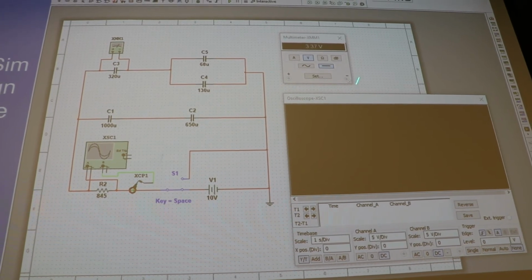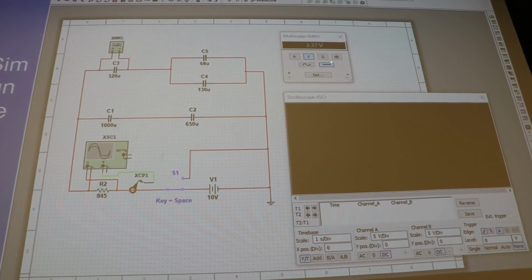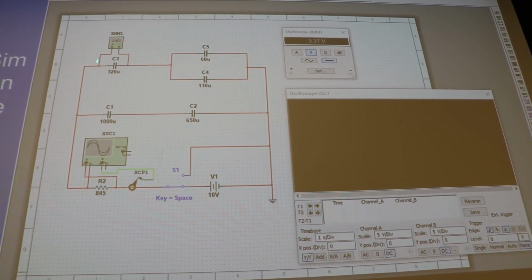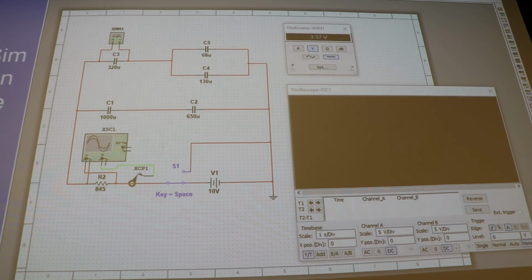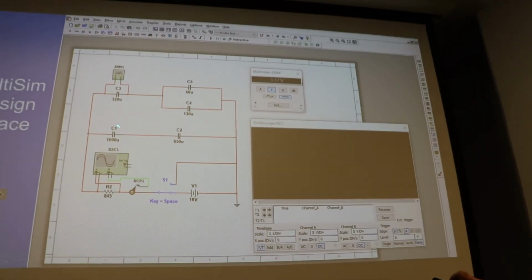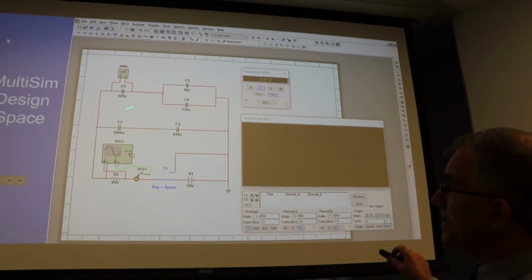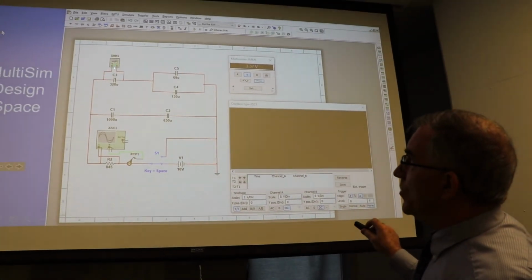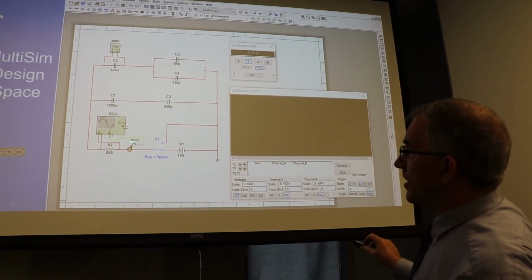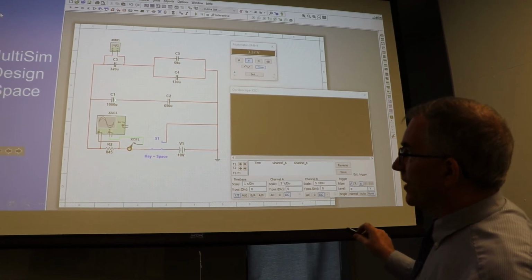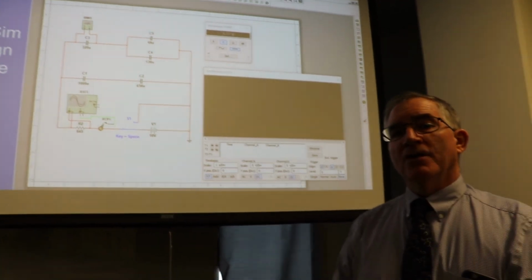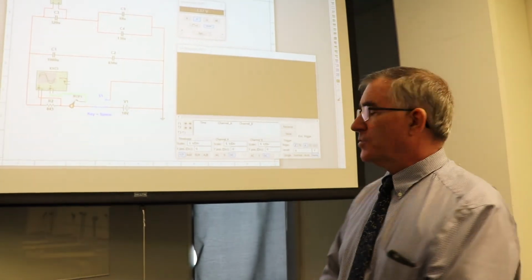Now, you could also have a voltmeter, which you will have, and this is set for DC volts, and you see the V right here, and that's for this particular capacitor right here. So once your circuit gets all charged up with a certain voltage, you'll go around and measure the voltages on all the different capacitors by moving this thing from capacitor to capacitor to capacitor. And you're going to move this guy around and measure the current going to all these capacitors, and you'll have to do an integral to measure the charge that's going on those capacitors.